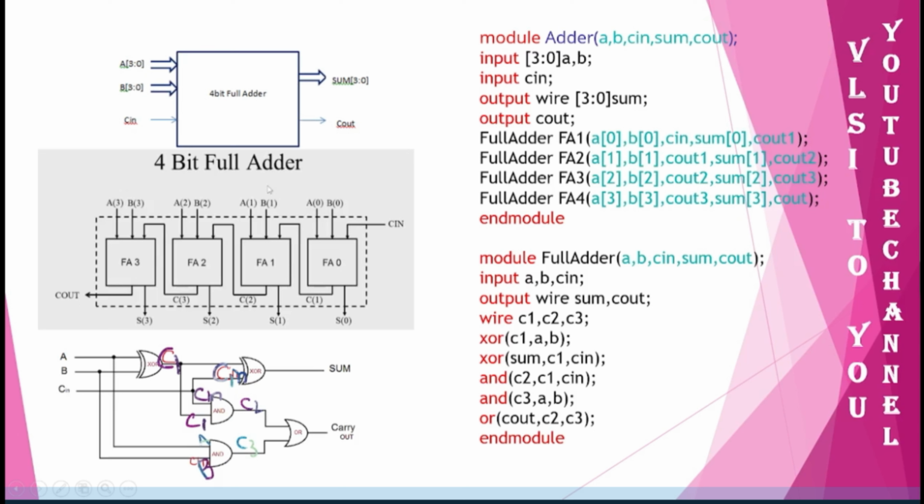Why is it? Because one C out is given as input to the next stage. Now if you see here, this is the stage and this C1 is given as input to another full adder. So that is why the C out is only 1 bit. Now when you are going to write the code, since A and B are 4-bit wide, so 3 down to 0, but Cin is only a single bit, so that is why it is input Cin. Okay, and output wire.